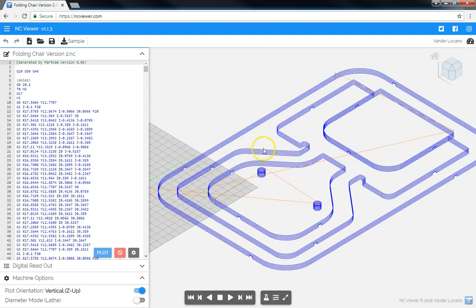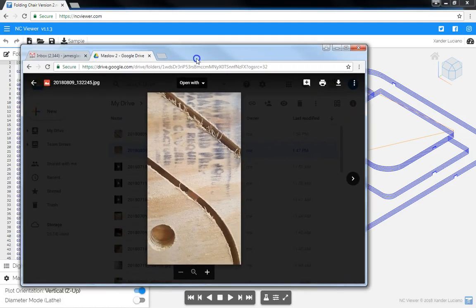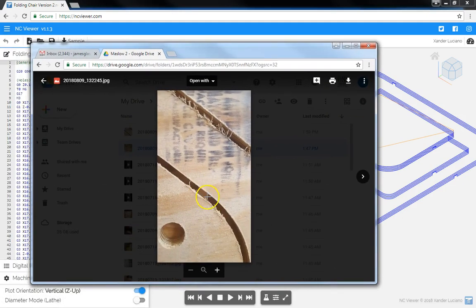So at first, when you're looking at it, if you've got multiple parts, and even if you don't, you should be looking for these little upticks at the bottom row. These are called tabs. Now, a tab is a little piece of leftover wood that the router does not cut out.